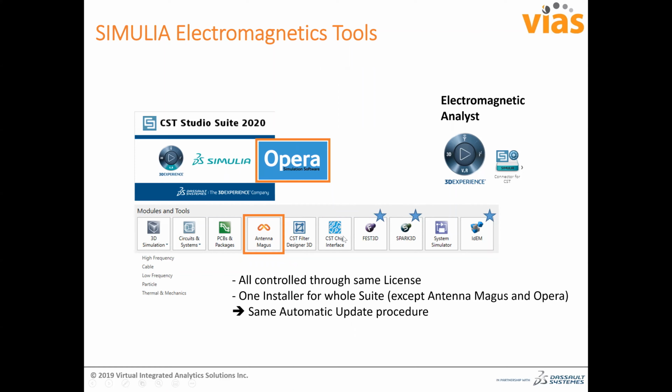The CST chip interface tool: if you have a Cadence Allegro board file, you can bring it into CST and it will automatically convert it into a 3D file. On the 3D file, you can then do the EM analysis and see the electric field and far field, if it is an antenna. But if, say, you have a DDR4 channel, you can see the effect on the transition on the motherboard when the DDR is connected, and how it affects the data rate.